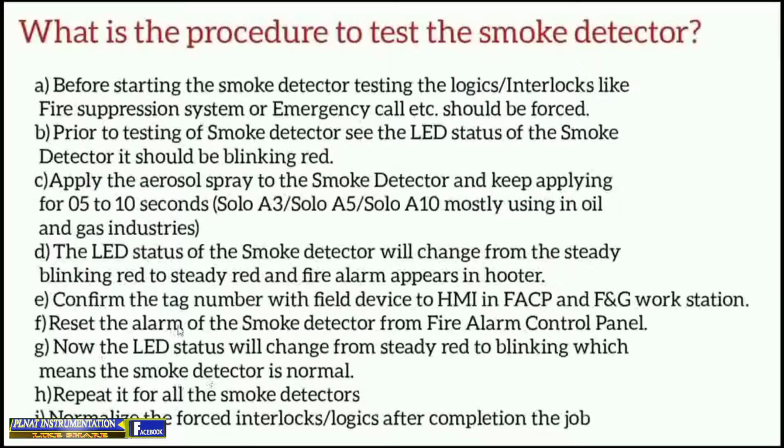Reset the alarm of the smoke detector from fire alarm control panel. Now the LED status will change from steady red to blinking, which means the smoke detector is normal. Repeat it for all the smoke detectors. Normalize the forced interlocks logics after completion of the job.